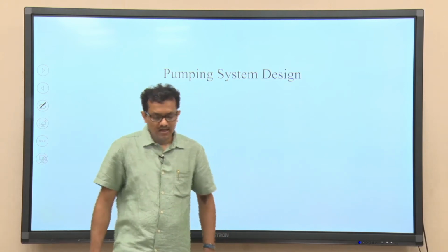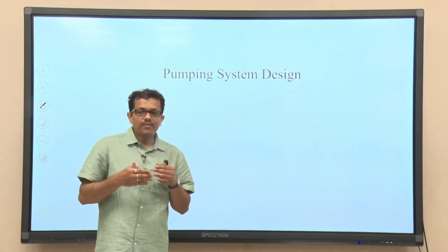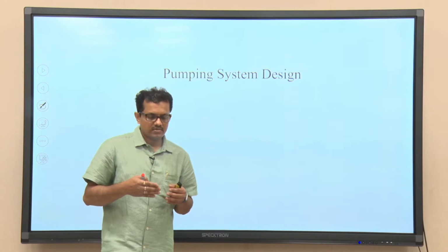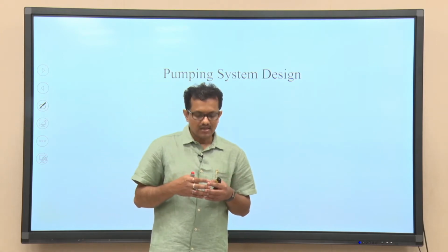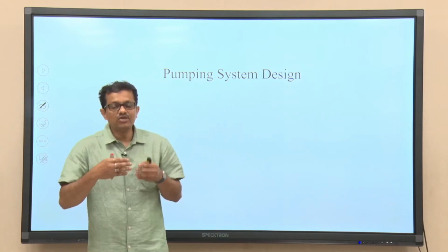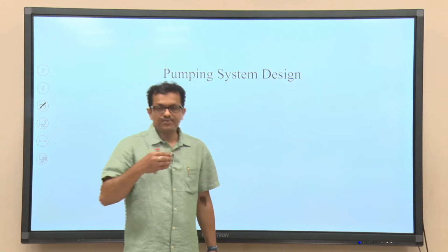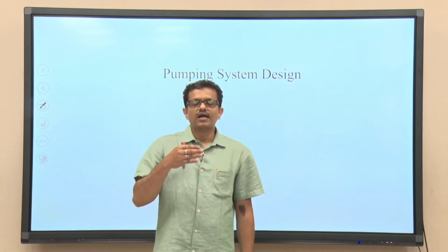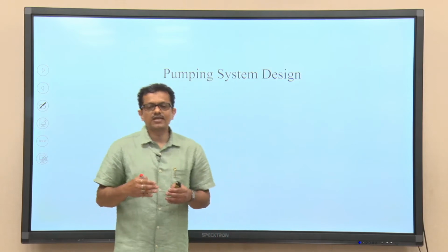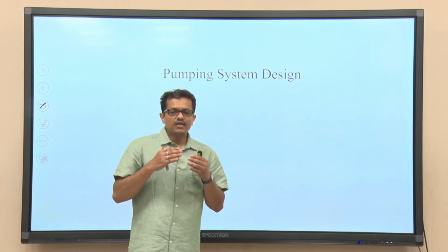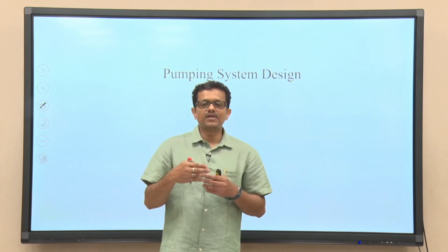So, whenever a pump or pumps are installed in a pumping station, it is very much essential to know the system resistance. Basically, before procuring any particular pump, it is necessary to have information about the system in which the pump is going to be installed.